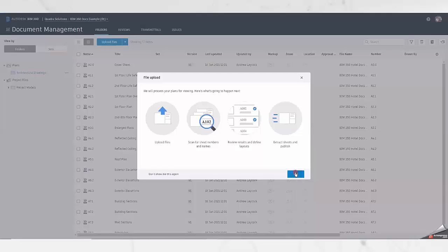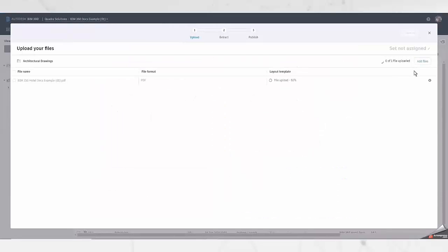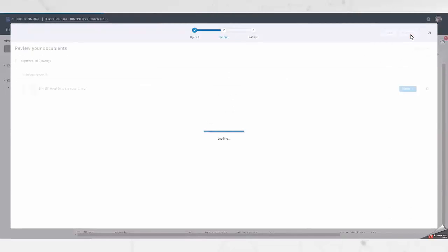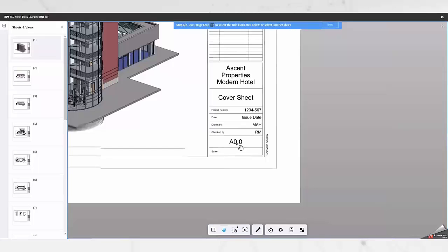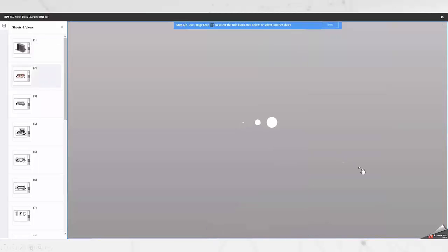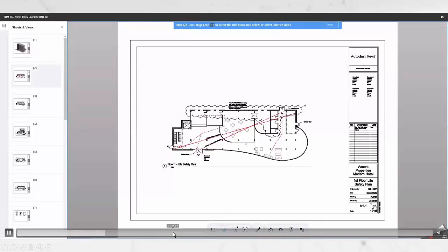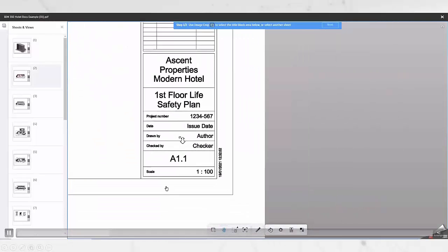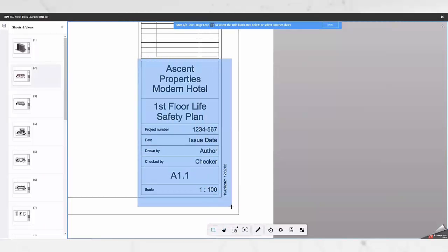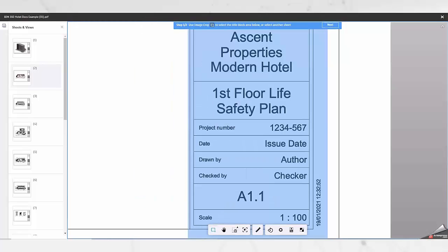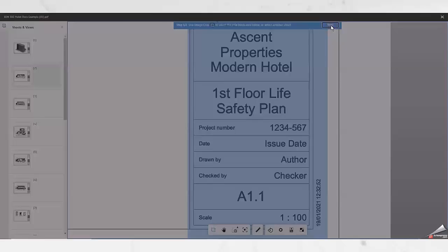I did a scale attribute, which you didn't see being created. So in this next part of the video, there'll be a slight change. The change being that I'll have to go to the second page because there's no scale on the first page because it's a cover page. So I'm going to define a brand new title block extraction set. I'm going to make sure I incorporate the text there. So I've moved to this one because there was no scale in the previous one, and I'm going to make sure I incorporate that so I can pull in the issue date. Sorry, the printed date.